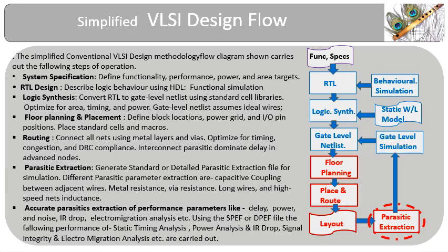At advanced nodes, interconnect parasitics dominate delay and must be modeled accurately. Parasitic extraction captures parasitic elements of capacitance, resistance, and inductance of the layout design. The extracted parasitic data is superimposed on the design and used to carry out static timing analysis, power estimation, IR drop evaluation, etc. The various steps shown in the flow diagram ensure that the fabricated chip realizes the desired functionality.